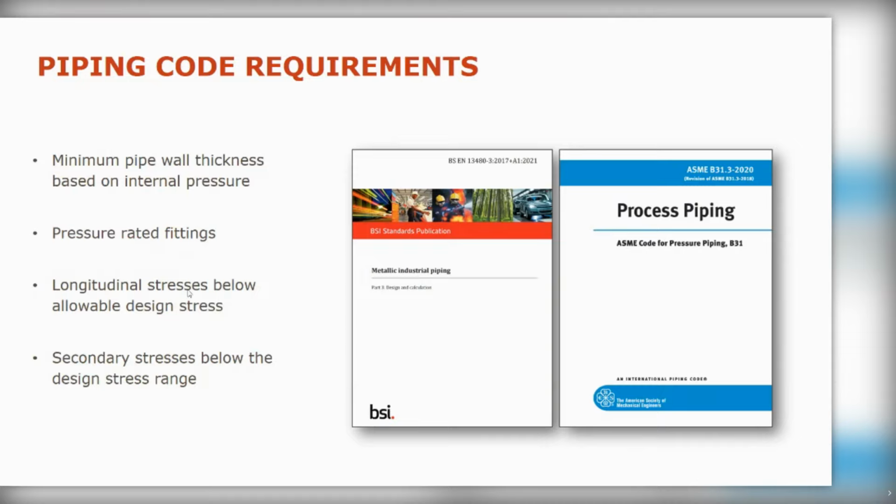That's a secondary stress. Primary stress is the one where there's a force acting upon it, and it doesn't matter, it can start deforming, but the force will still be there. So the pipe has to withstand the force and basically stop this movement due to force. And this is why for primary stresses you put more supports, counteract the force, you're done. Or if it's internal pressure, put a thicker wall. You can hold that force from the internal pressure, you sort it, you're fine.